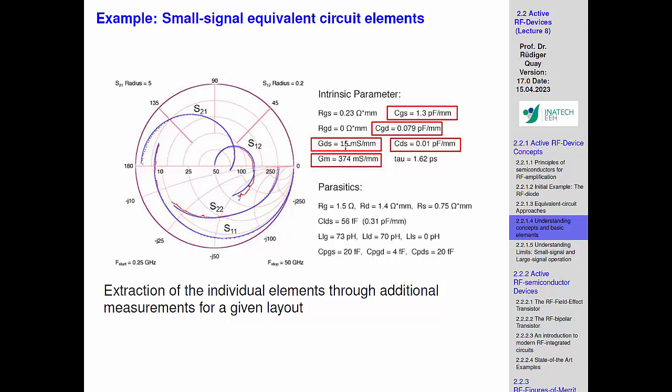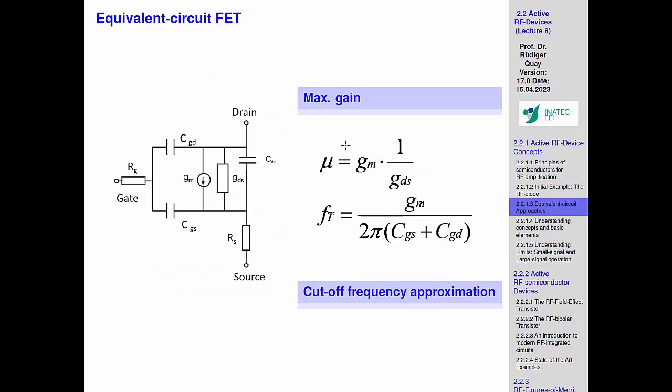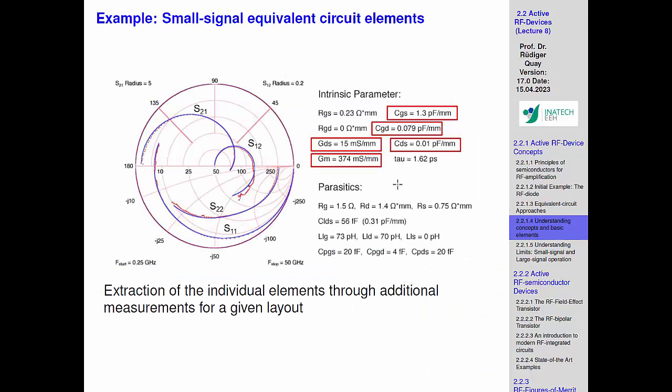It's a factor of 25. Yeah, so there you can really directly see the maximum gain which can be achieved, because here you get the direct reading. It's 375 by 15. So if you get the slope down and the current change up, you win amplification. Yes, it's a very simple but useful argument.